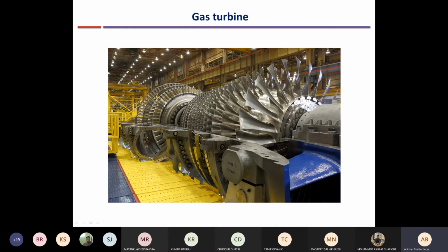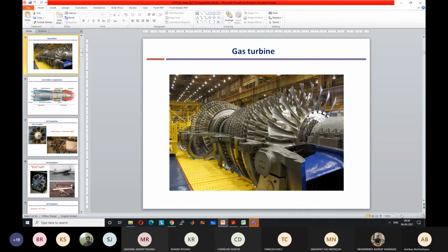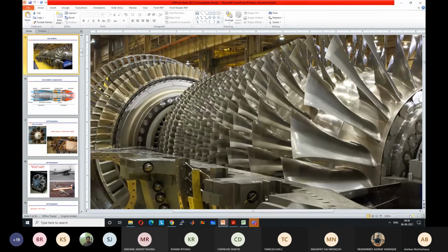So you will be able to see, it's not very clear from here. These blades are actually much more twisted, the turbine blades. So large amount of change in angle occurs in the turbine blades as compared to the compressor blades, which are not twisted at all. Means it is very less twisted. Okay, it will be twisted as you can see, but very less twisted. So the more is the twist, more will be the change in the velocity, and more is the actual change in the pressure.